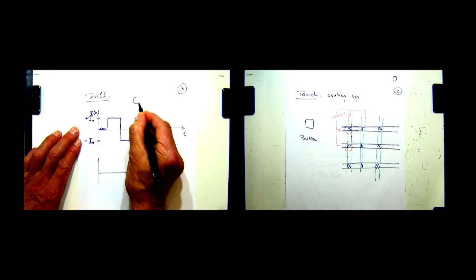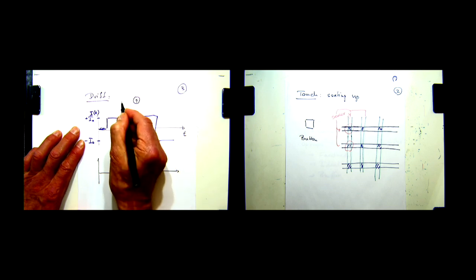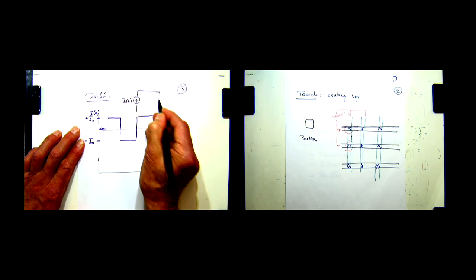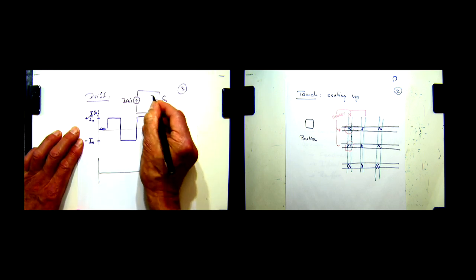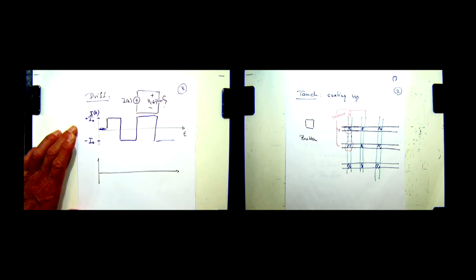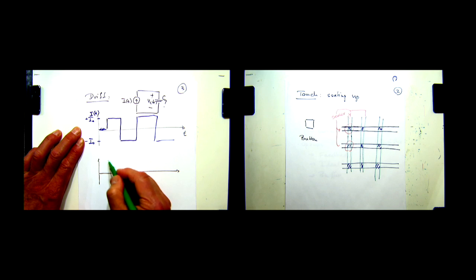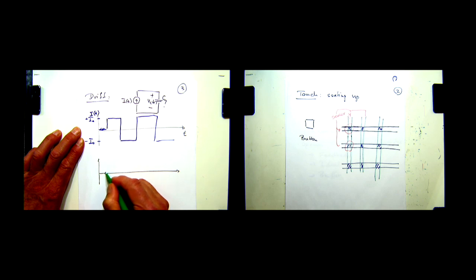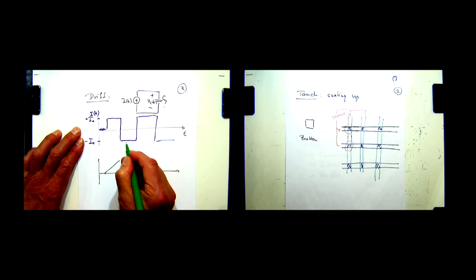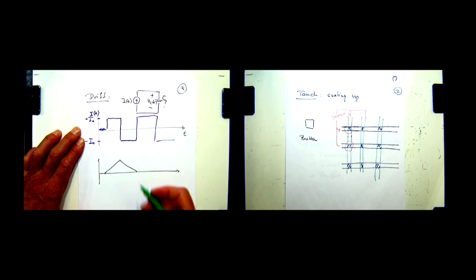So basically what we had is this current source, I of t, that has this square wave characteristic, and we applied this current to our unknown capacitor. So this is C, question mark, Vc of t. Okay? And Vc of t, we expected that here the current is positive, so the voltage is going to increase because our capacitor acts as an integrator, and then the current is negative in this part here, so the voltage is going to ramp down again, and this continues like that.